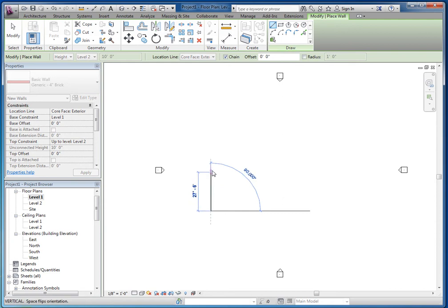But I'm going to leave these defaults alone, and I'm going to draw a small structure by left clicking in the drawing editor, and I'm going to move the cursor straight up and see the dotted lines. That's like your ortho mode. It indicates that you're at 90-degree angles. And Revit is kind of unique in that it works with feet and inches, which is a little bit different than what you've worked with in the other applications so far.